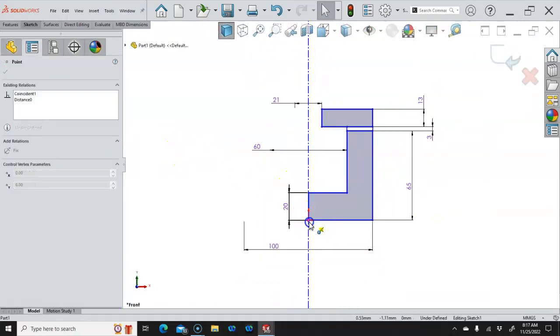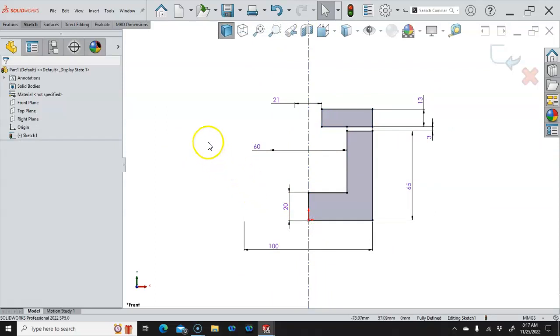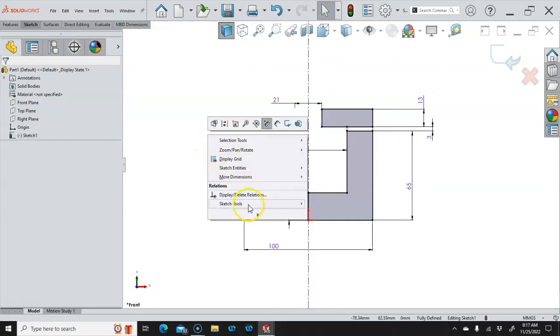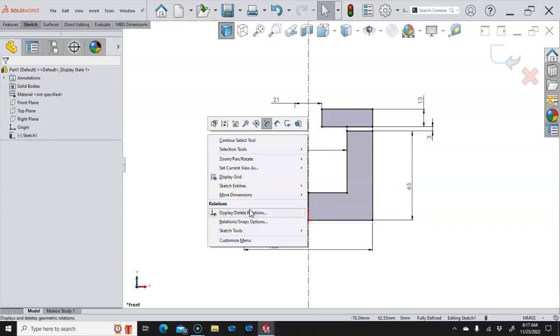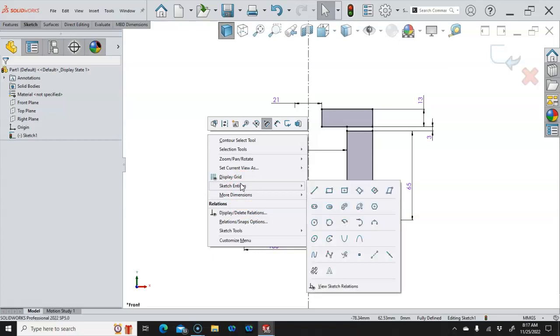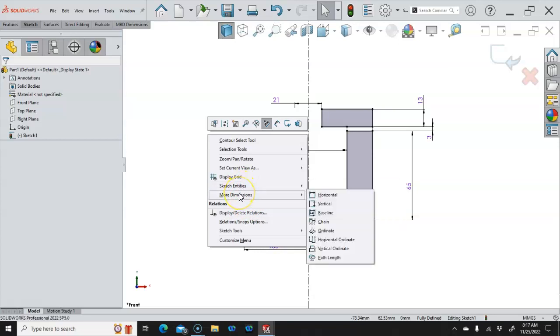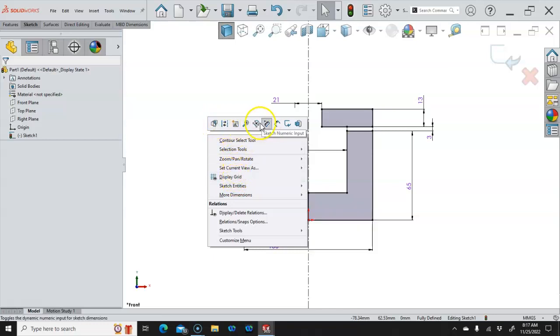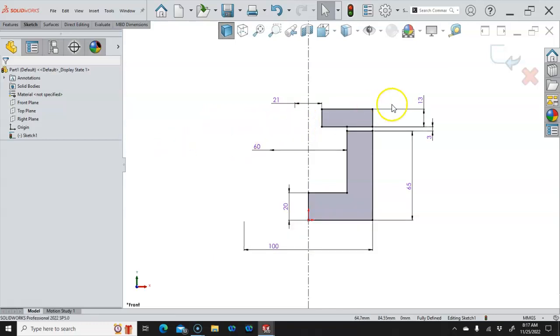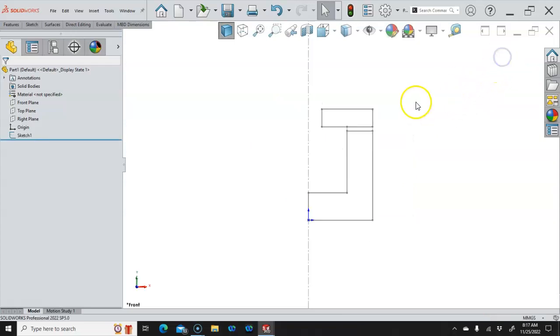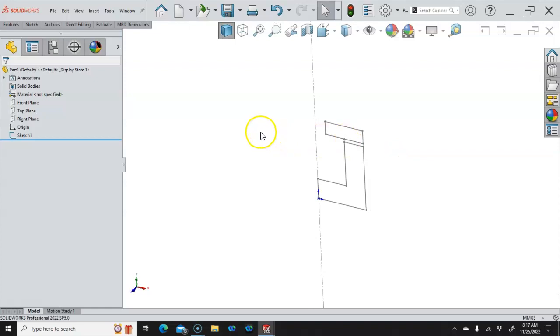If the dimensions are gone, then this would be a good place, and I'm not real fond of it, but I'll introduce it. Let's see if I can find it. Nope, not seeing it. All right, so if the dimensions weren't there, we do have an auto dimension, set the datum, have it create these, and they're pretty much to scale. The problem with auto dimension is you end up with a lot of dimensions that you probably don't really need. All right, so we're in the part.